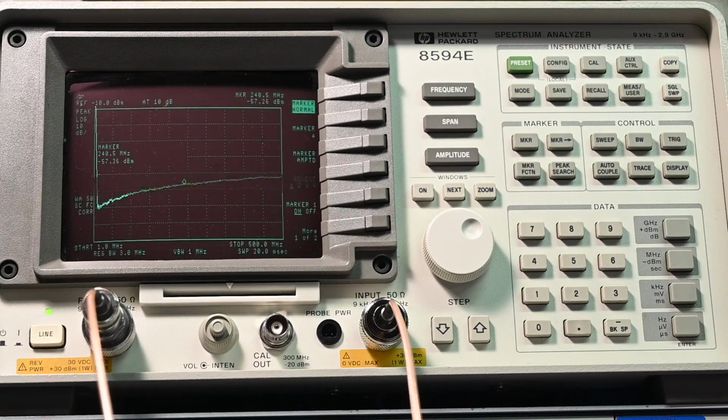That's really pointing to maybe a problem with that assembly number 10. Now, the switch that's in there, that RF switch, it has a control voltage, and I think that voltage needs to be checked just to make sure that that's correct and that it's driving the switch properly. And if that voltage is correct, then I really think that A10 has developed a fault.